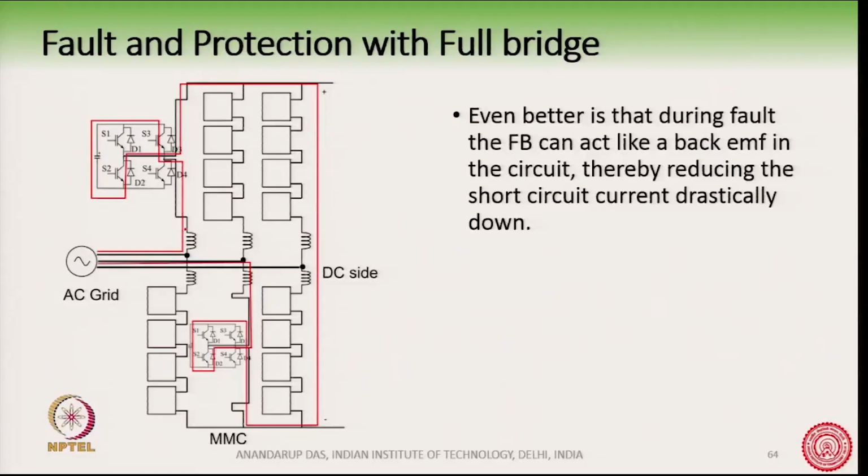So, during fault condition you can make sure that the controllable voltage sources in the arms are adjusted in such a way that you prevent the current flow. Okay.